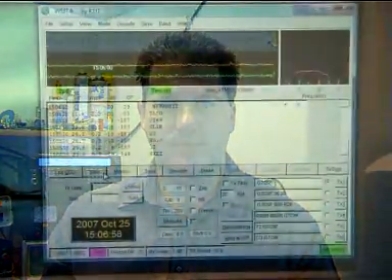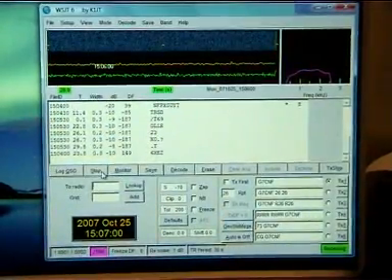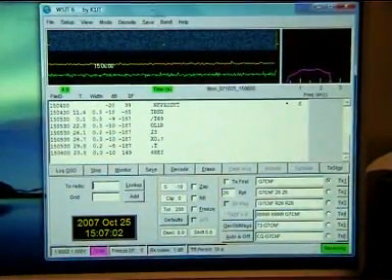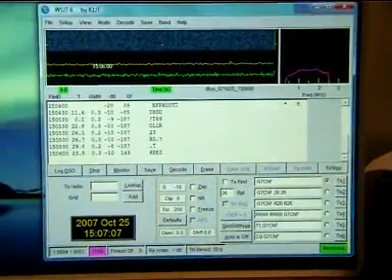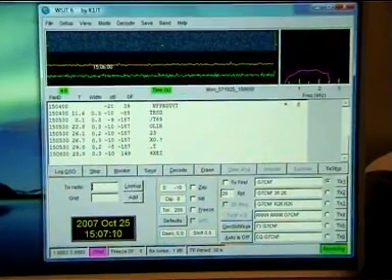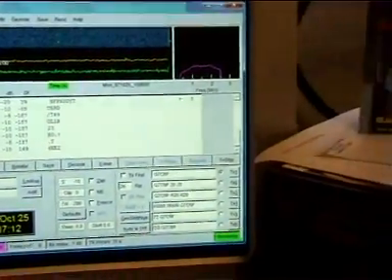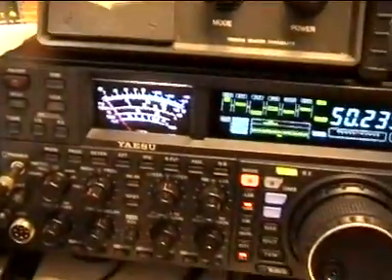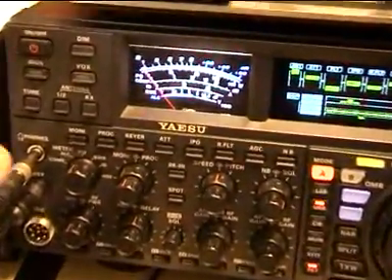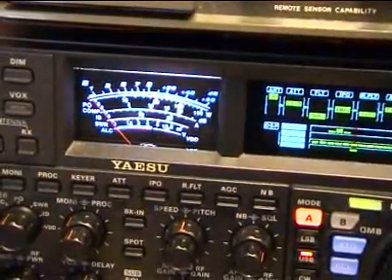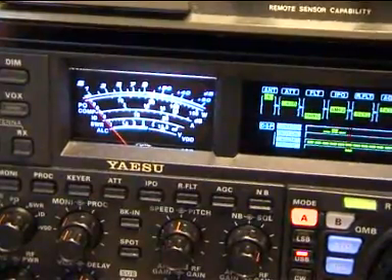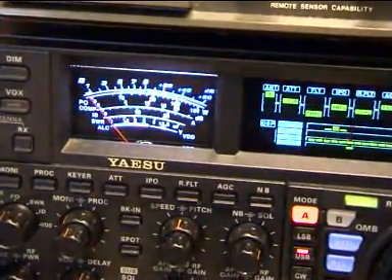Now it's time to turn our attentions to the transmit audio levels. This is very critical also, as too low an output and you could be doing yourself out of a reasonable output power. Too high an output and you could be generating some distortion. For this, I recommend that should you have the facility, please adjust the meter on your radio to ALC. That will help you determine whether the output from the PC to your radio is acceptable or too high.